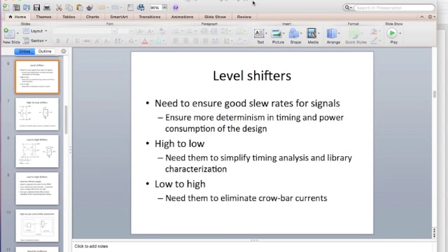Whereas if I have a very, very slow edge rise time, and I put a little bit of voltage noise, I'm shifting the whole edge up or down. So the point at which it intersects the logic trip point voltage value, that time will fluctuate a lot depending on the amount of voltage noise you put in.